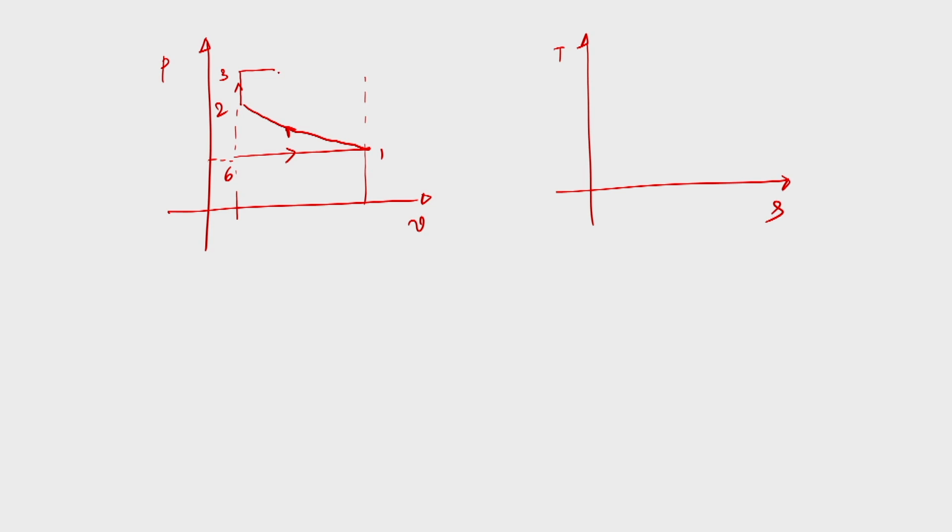It is very important. Then again we have isentropic expansion. Sorry, let's say this is point X, this is point 3 and this is point 4. 3 to 4 is isentropic expansion and 4 to 1 is exhaust blowdown, or I can say 4 to 5, and 5 to 6 is the exhaust stroke.